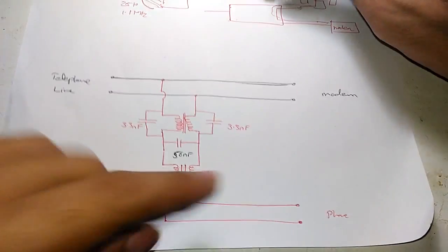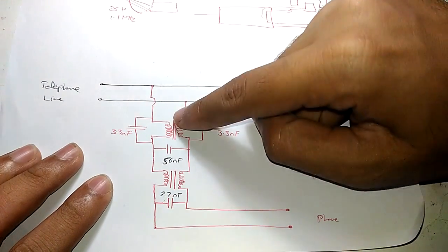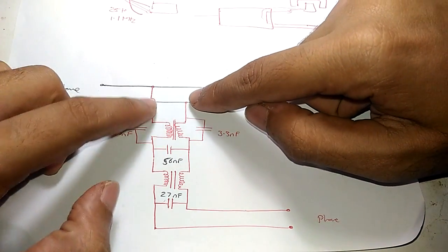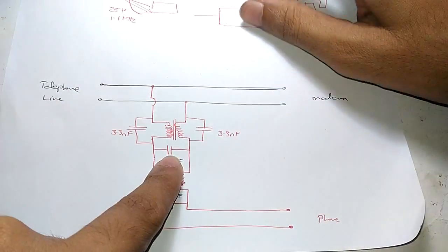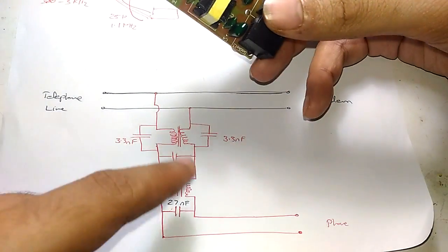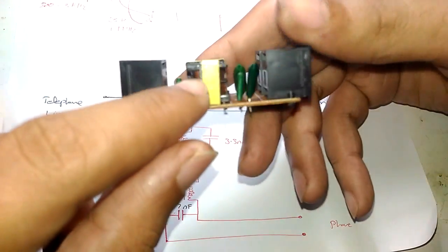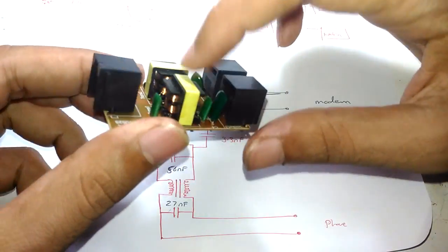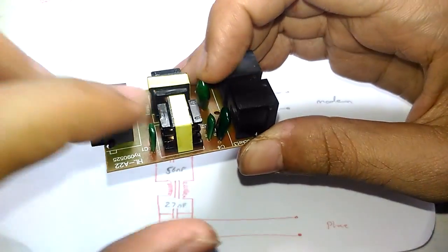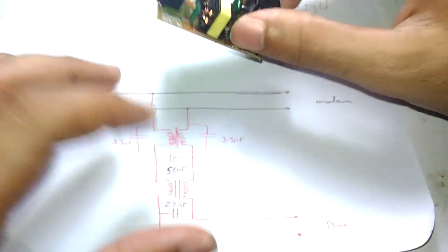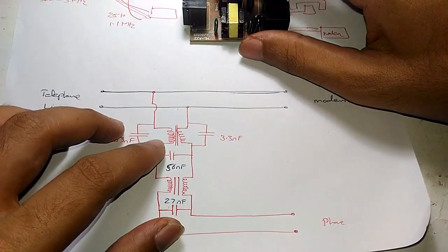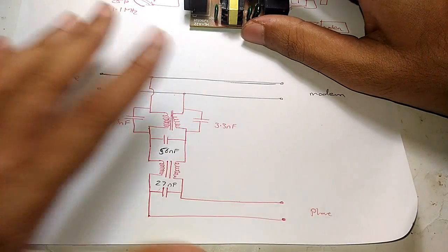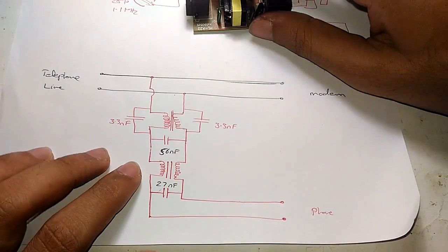And the only problem that this can cause is, if the splitter is bad, it can cause problems with your phone. Because if you take a look, these are actually two inductors in series for each line. On every line you have two inductors, and I don't have an LCR meter to measure the inductance of this thing, but it will be quite high because of the frequency that it is designed to block. Also, because it has this ferrite based winding, the inductance is going to be much higher. And it is an LC, inductor capacitor filter, which is normally used for high frequency applications.